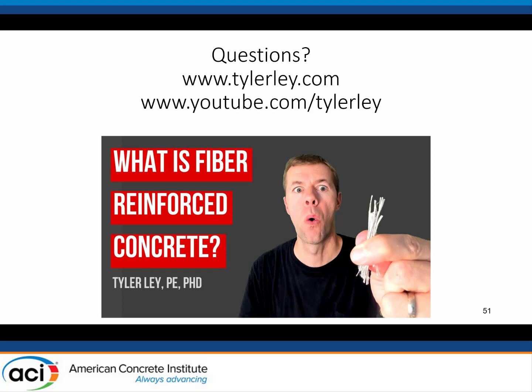I would probably go out there and look heavily. Maybe it's too late. Maybe you can't do anything about it. But in place concrete strength makes me feel a lot better than cylinders. But I would look carefully about how those cylinders were handled, and that may be an indication of what was going on. Right, because if they were dropped or they were handled inappropriately in the first 2 days, that could have an influence. Or if they weren't cured correctly, as in they were allowed to get super hot or super cold, or if they didn't stay wet.